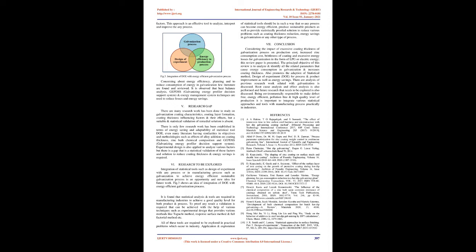To analyze the root cause of these effects, root cause analysis is done. The tool selected for this analysis is the fishbone diagram. Fishbone diagram is also named as cause-effect diagram. Fig. 2 shows the fishbone diagram for the galvanization process. This diagram is divided into three parts: effects, root cause of effects, and causes of root cause. The long straight arrow in the middle is considered as the fishbone that indicates the root cause of effects, that is excessive zinc coating thickness. There are various causes of excessive coating that are termed as causes of root cause.